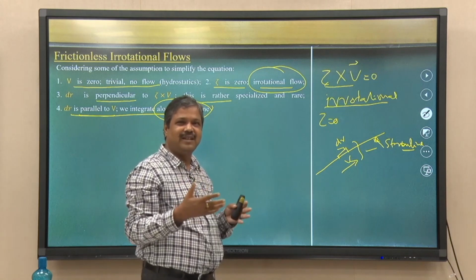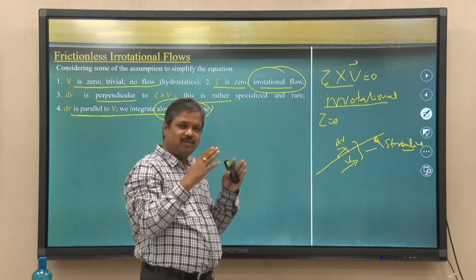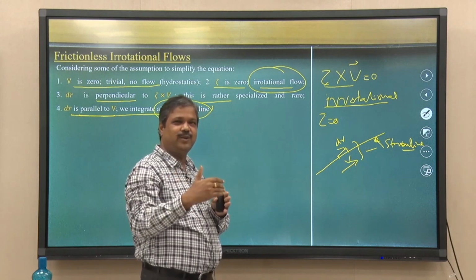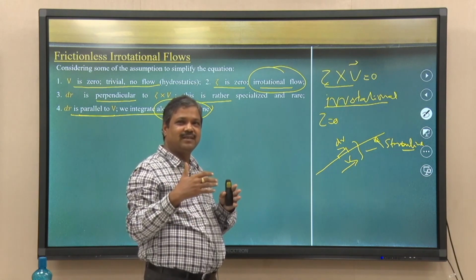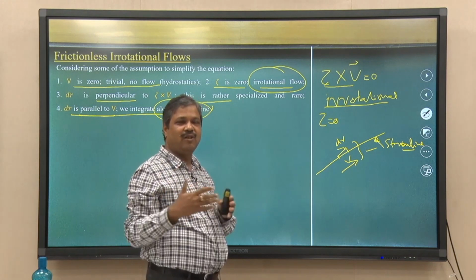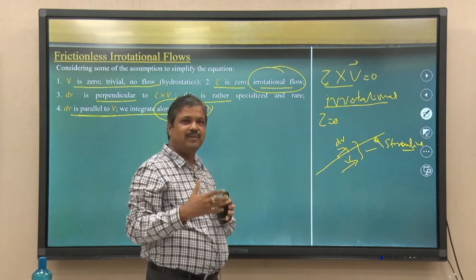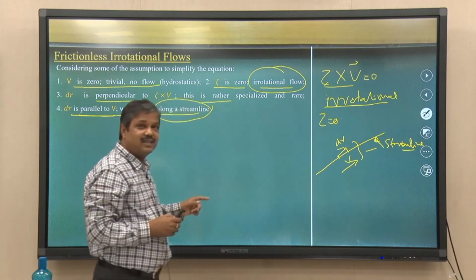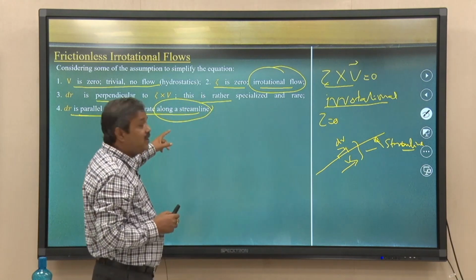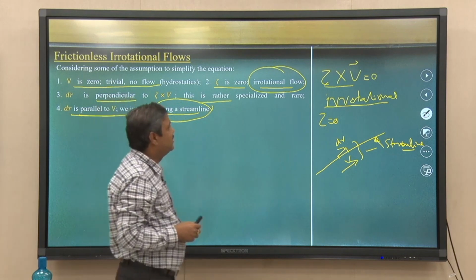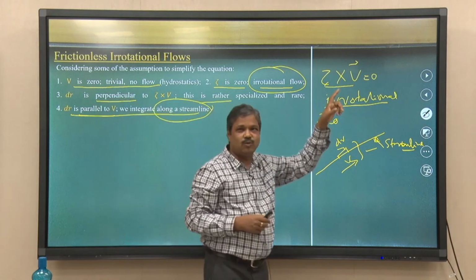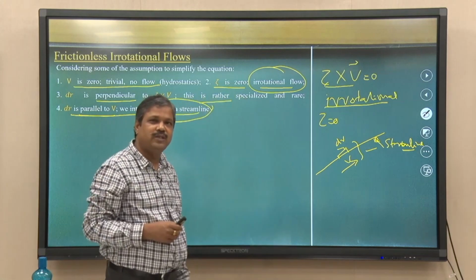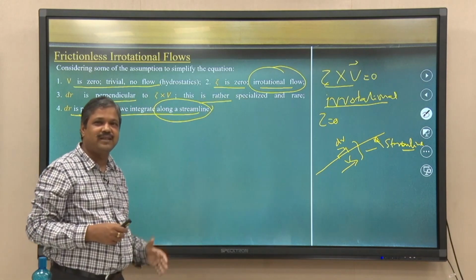We derived the linear momentum equations from the Navier-Stokes equations with these assumptions, like the Euler equations. Looking at the vector expansion of the Euler equations, the convective acceleration terms, again we come to a condition that along the streamlines tau cross v is equal to 0. So, that is valid along the streamlines.